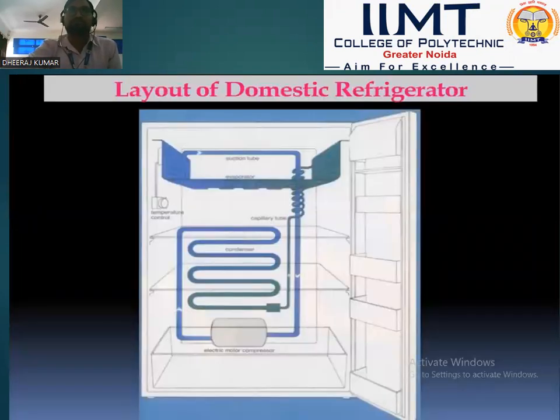This is the layout of the domestic refrigerator. The domestic refrigeration system works on VCRS, the vapor compression refrigeration system. The four main parts are compressor, condenser, evaporator, and expansion device. The compressor compresses the refrigerant, pressure and temperature increase, and high pressure, high temperature refrigerant is supplied to the condenser. This is called the condenser. The condenser rejects sensible heat as well as latent heat, and the refrigerant converts into saturated liquid.